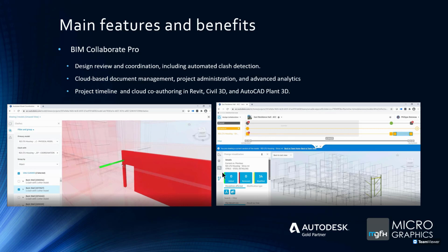Right, so design and review, you can coordinate, basically the clash detection. Meaning that if there are other stakeholders, structural and MEP engineers, and everybody uploads their models, you can very quickly and easily see where clashes might happen, and it highlights those. You can mark it and send it off to the particular consultant, and they would then update their model. You'll get notified, and you'll do the clash detection again and solve the problem before it gets built on site.